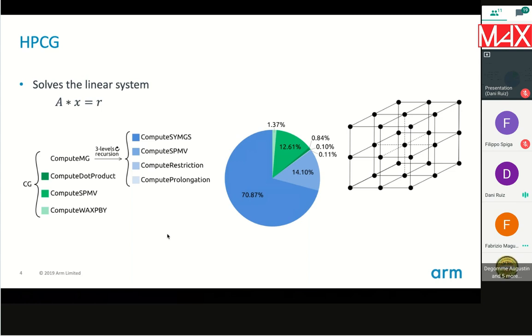How does it do this? It uses a conjugate gradient method. So basically, it implements an iterative solver. The conjugate gradient is preconditioned. For the preconditioning, it uses a multi-grid method with a Gauss-Seidel on it. The rest is a conjugate gradient.